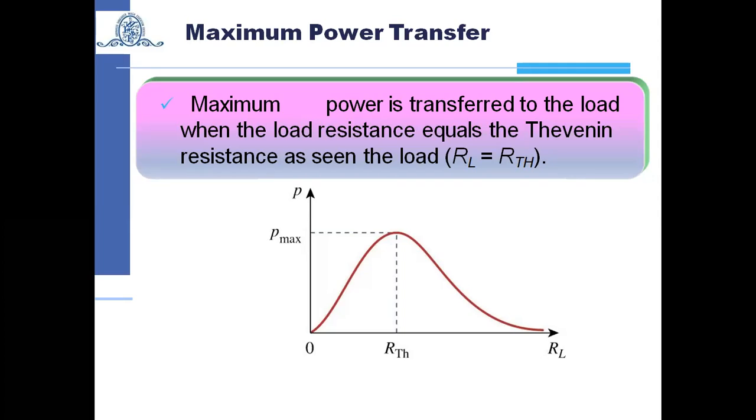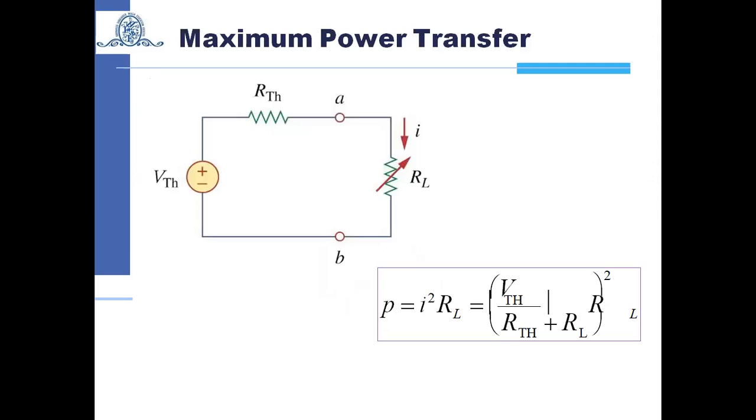the open circuit voltage and a resistance that is in series with that voltage. But here, if we are supposed to calculate the maximum power, the maximum power theorem states that maximum power will get transferred to the load if the value of RL equals RTH. So if you see, when we have any circuit, we can convert that circuit into a Thevenin equivalent circuit.